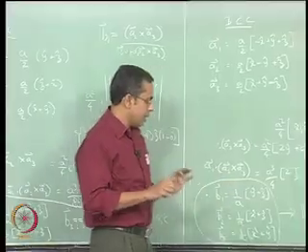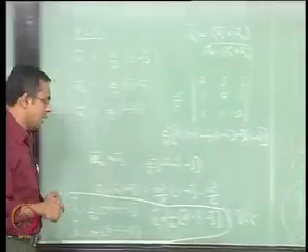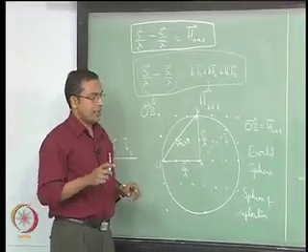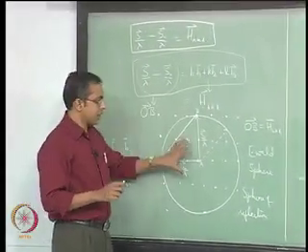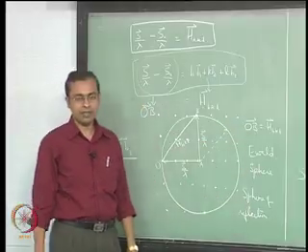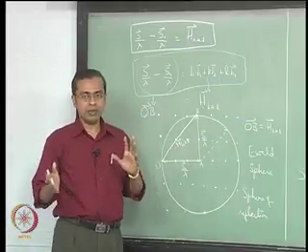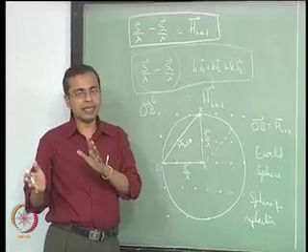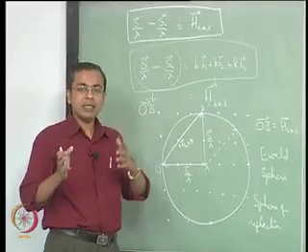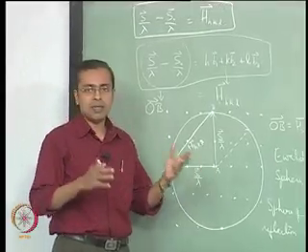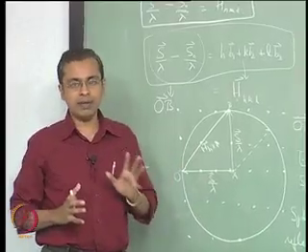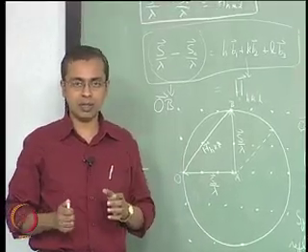So to finish this class, I want to just highlight a few points that I made throughout this class. The first is that the reciprocal lattice notation, which is represented in the form of this Ewald sphere, tells us how the matter is interacting with the radiation, or waves in this case, and tells us when diffraction will occur and when diffraction will not occur. It gives us a nice, elegant geometrical look at when diffraction will occur and when it will not, okay.